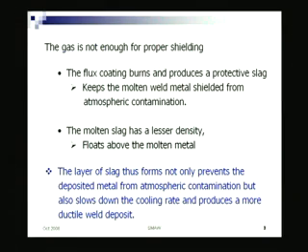That is what is referred to as welding fume. When you do manual arc or shielded metal arc welding, you will find a lot of fumes getting generated. They are purposely generated, meaning the flux composition is such that those fumes are generated, because those fumes are needed to give a coverage to the arc column as well as the electrode tip.